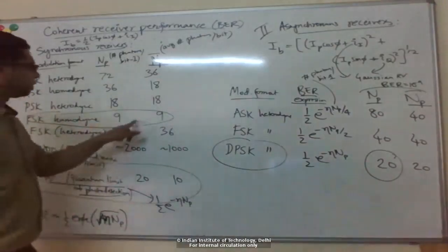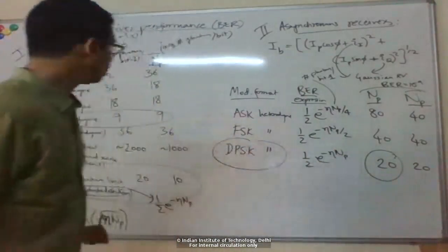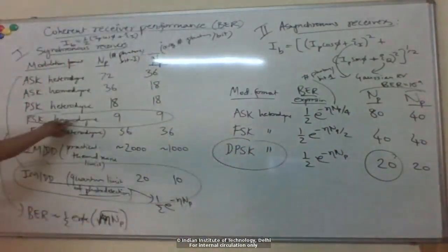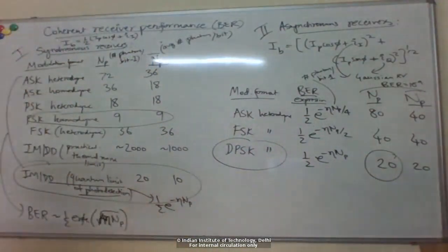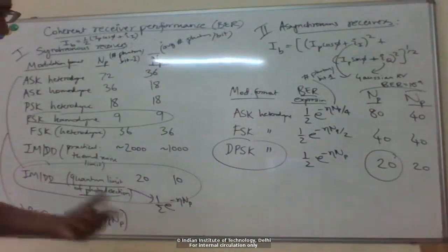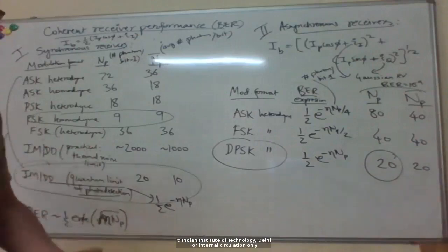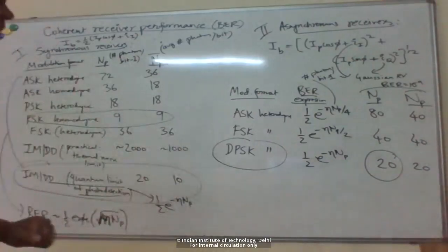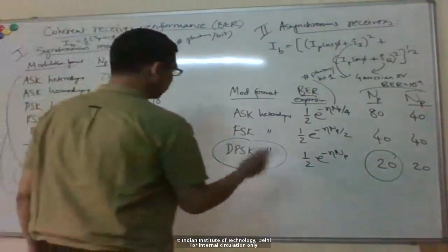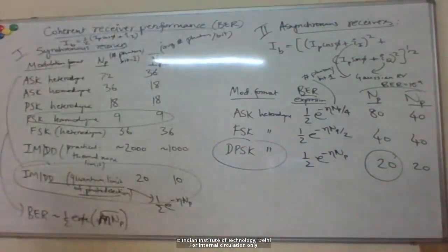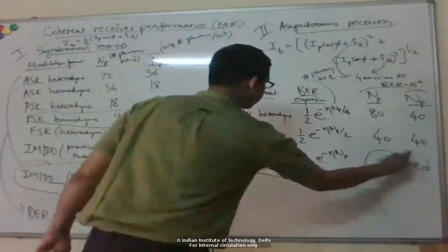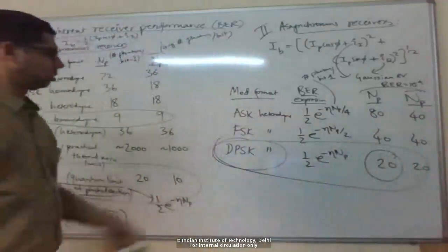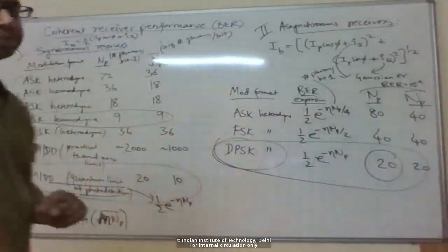So maybe a factor of 2 better than what you can do here, but again, this requires much more stringent requirements on my receiver electronics, my transmitter laser, local oscillator laser, a lot of things, right? So if you look at the trade-off between implementation complexity and the actual sensitivity you get, this comes out to be most viable.